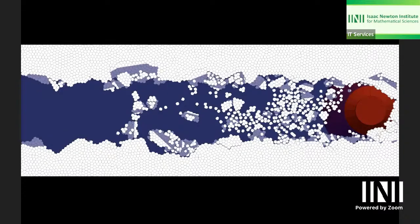Here's an example of the work that I often do. Here is an offshore wind turbine foundation, which you will see in later slides as well. There is an ice field moving in this picture towards the left and colliding with this structure. The structure is about 10 meters on the waterline. So that gives you the idea of the scale that I'm working on here. In this type of simulations, I would typically have the ice field being maybe 150 meters long, at least to see what is actually happening.